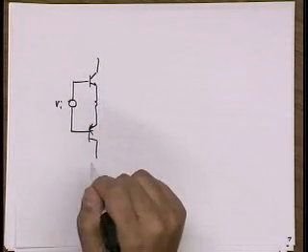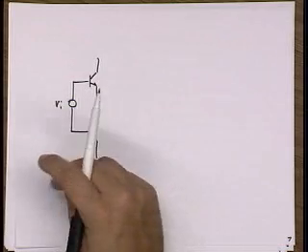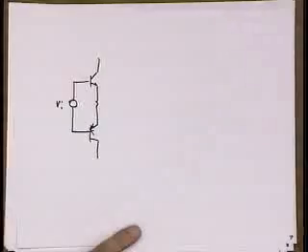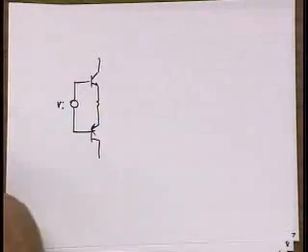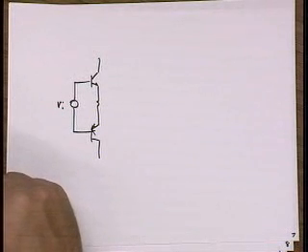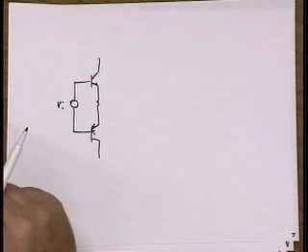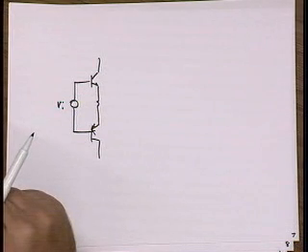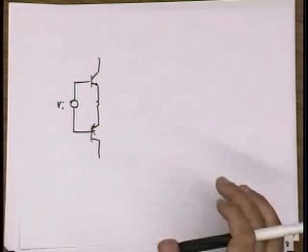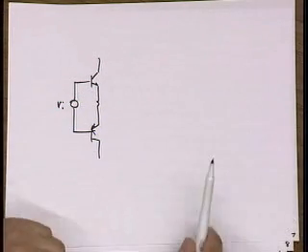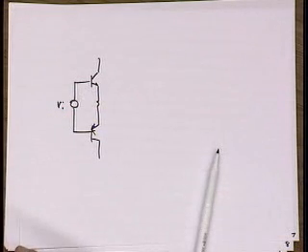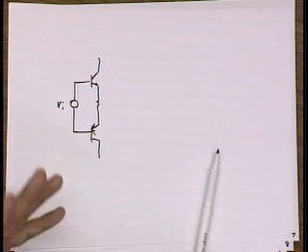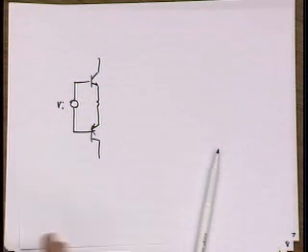Well, what's the input range for a diff pair? How much voltage does it take to roughly steer all the current to one side or to the other? Order of magnitude, don't have to give me the exact number. Is it 10 millivolts? Is it a volt? Is it 5 volts? No, it's actually much lower. It's on the order of 100 millivolts, about 120 millivolts.